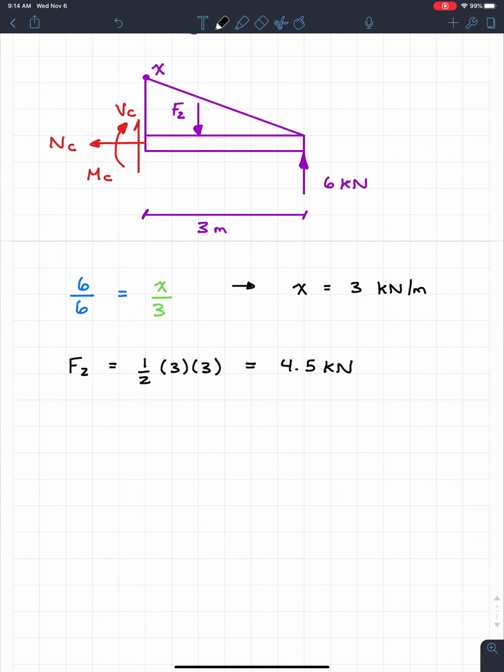So now if we look at our free body diagram, we have 3 equations and 3 unknowns, so we can solve for everything. And now this is where it gets really nice. Internal forces sound scary, but they're actually super nice when it comes to finding them at a point. Because if we look at our unknowns, one of them is perfectly in the x direction, one of them is perfectly in the y direction, and one of them is a moment. So it doesn't matter which equation I start with. It's impossible to have 2 unknowns in one equation.